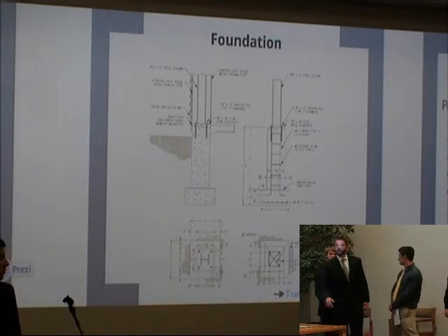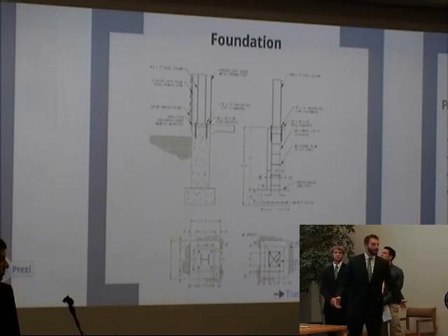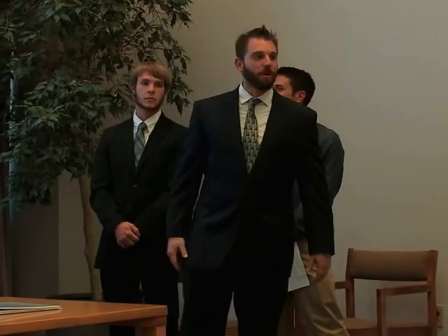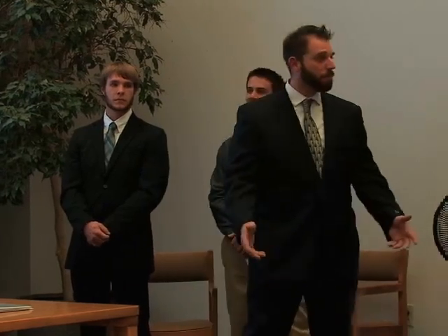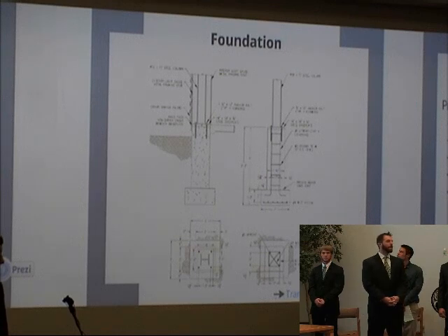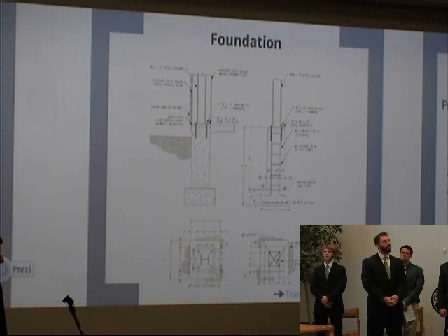Hi, I'm Greg Corey. Since I'm a geotech, I'm going to start from the soils and work my way up the structure. I'd like to characterize the soils in this area as being sand mostly. There are some sand and gravel areas. That's characterized from approximately ground surface to between 5 and 45 feet deep. At some spots in the locations of the actual structures, there is some silt mixed in with the sand. However, it's beyond 45 feet deep, so the appreciable stresses in those layers are going to be negligible.